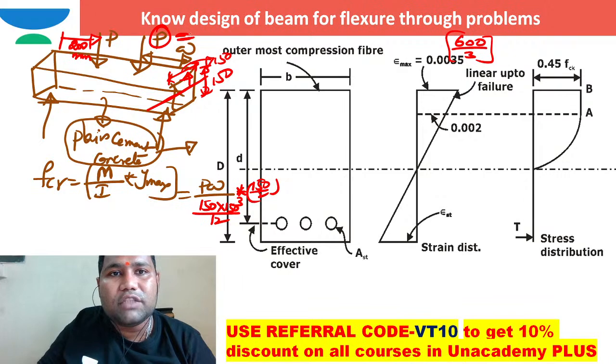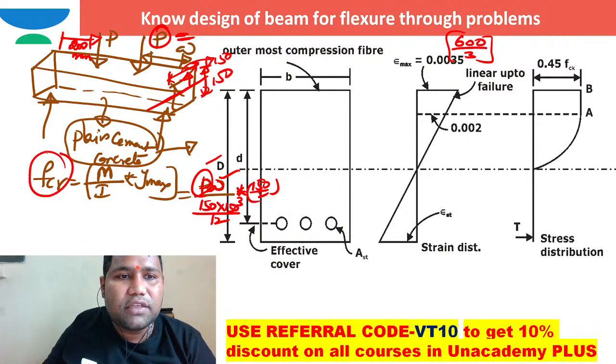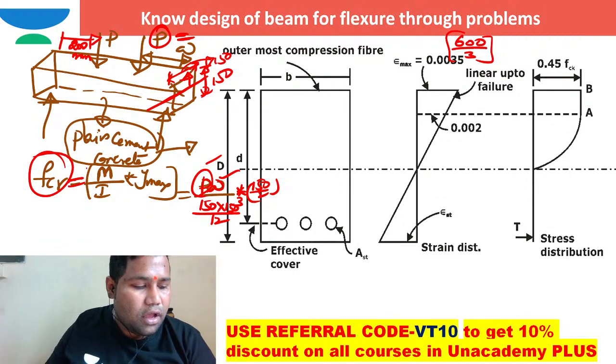P is the transverse load at which this flexural element is failing. This P can be recorded directly from the flexural testing machine. So P is known, A is known, so I can work out this fcr. This is how I can work out the flexural tensile strength of concrete.